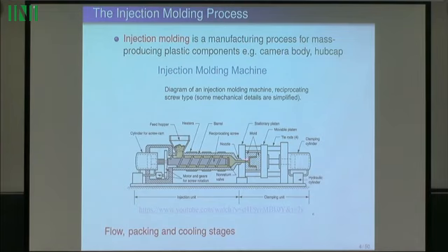Then you want to get rid of air bubbles and such like. And so they then increase the pressure and they pack more material into the mold. That's the packing stage. Then the mold is allowed to cool. That's the cooling stage. And then the part is ejected.